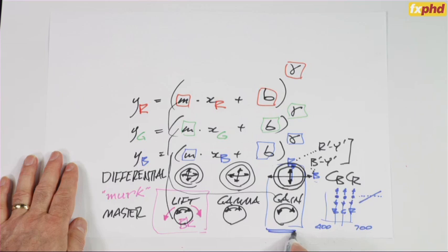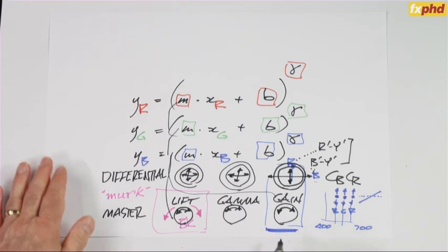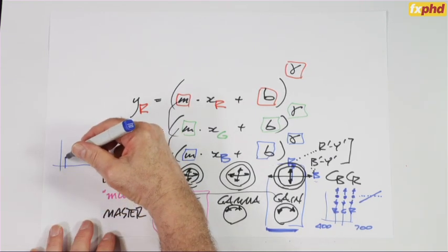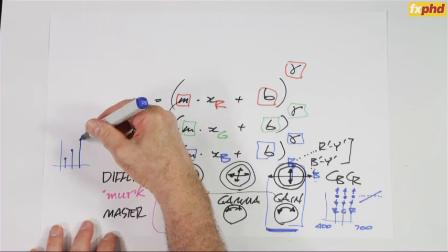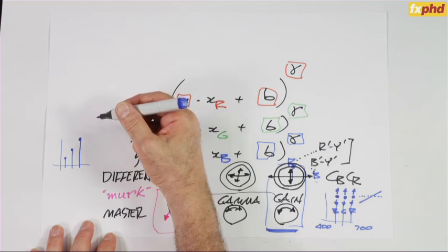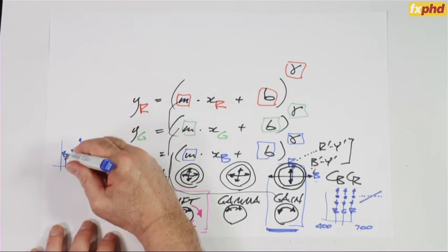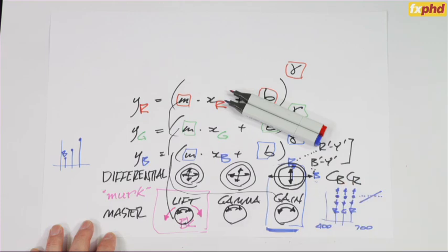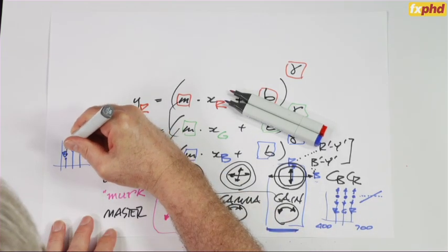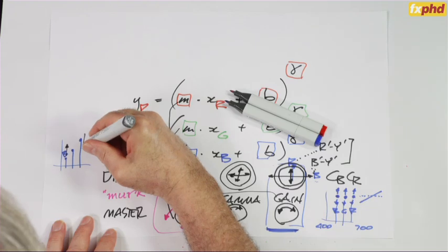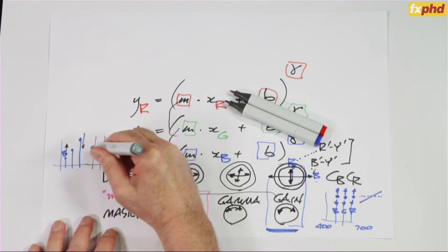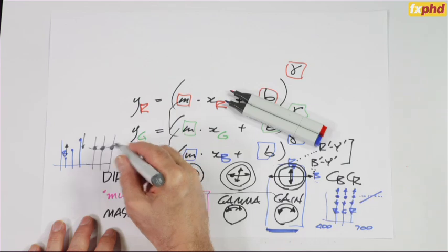And a very, very common use of the gain control is just white balance. Because if, when the image data came in from the camera, the scene was lit by tungsten light, tungsten is really deficient in the blue. So you would very commonly use the gain control to dial in some blue gain and dial out some red gain to neutralize the red, the green, and the blue to make a gray instead of a red.